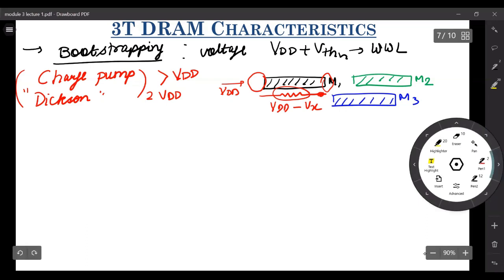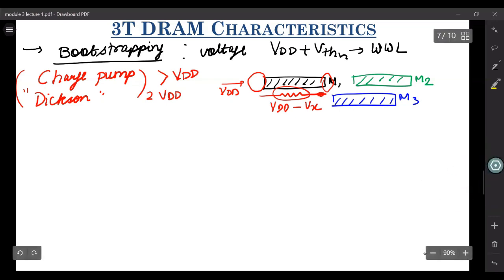So just to mitigate the impact of this series resistance, what people do is, so this was the top view. I mean, you are looking at it from the top. Now let me draw the side view. From the side view, let's say this is your transistor level. Immediately after the transistor level, you have this metal 1 connecting these several transistors. Something like this. Then there is this interlayer dielectric, which is called ILD.